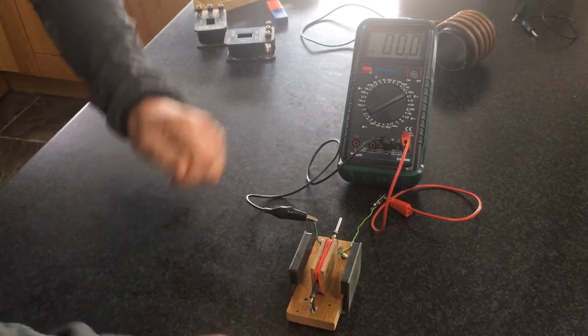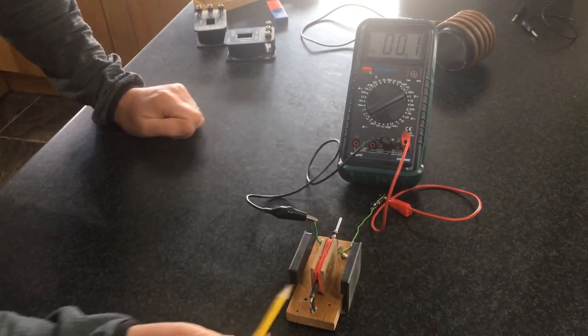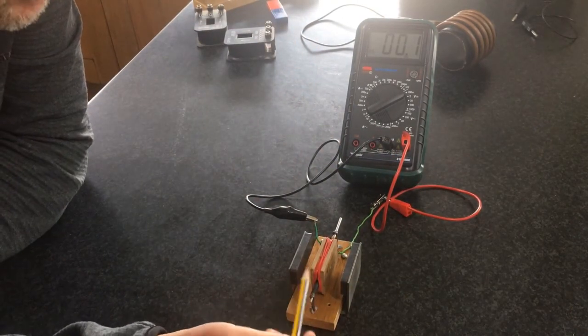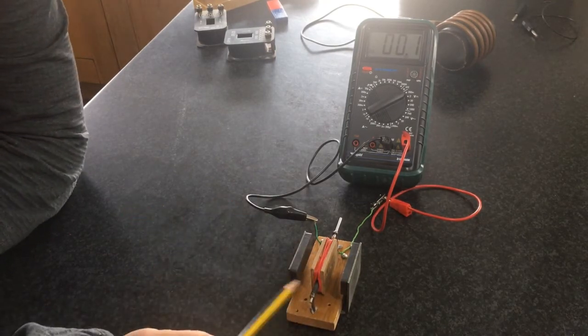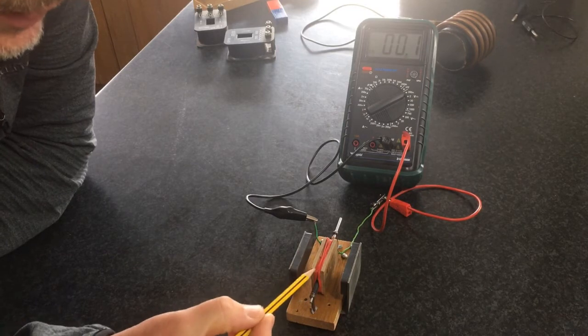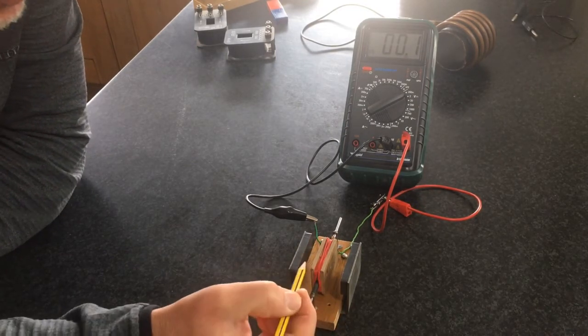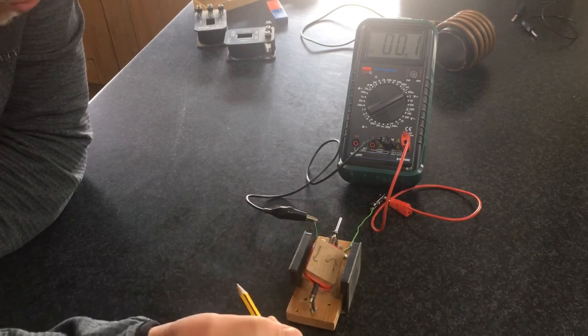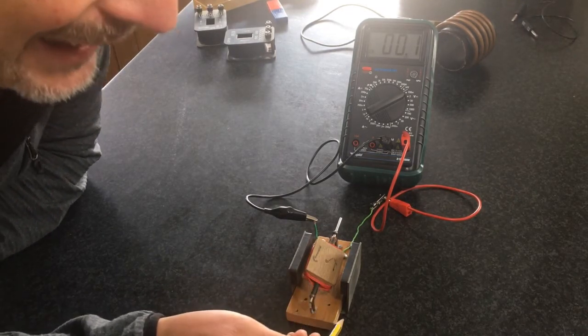Sometimes you'll have a rechargeable battery and you've got a handle and you can turn it. I've got a little radio like that, and as you rotate it, you're generating electricity and charging the battery up. So this is a dynamo. The only difference between a DC dynamo and an AC generator is that in an AC generator, you're rotating it and you're not swapping the connections around. In a generator, you're going to make AC.